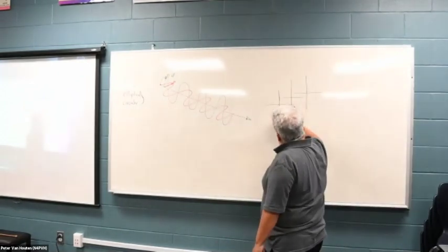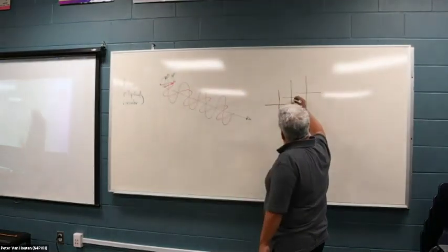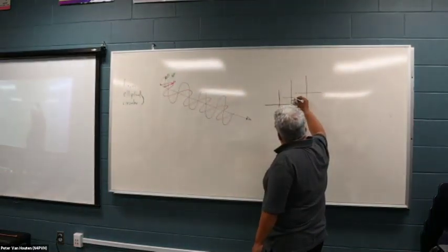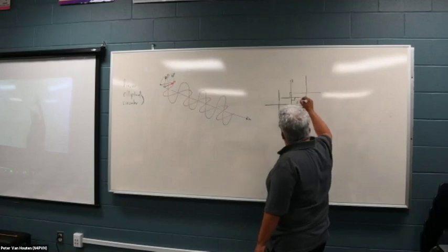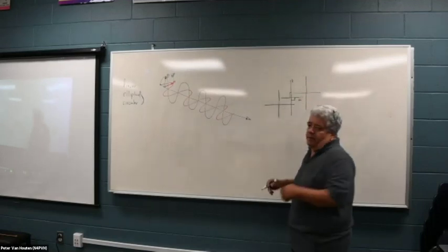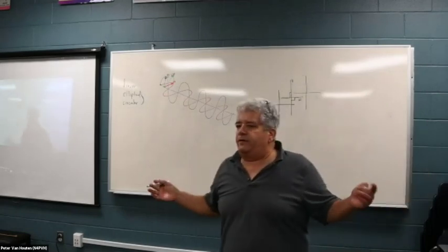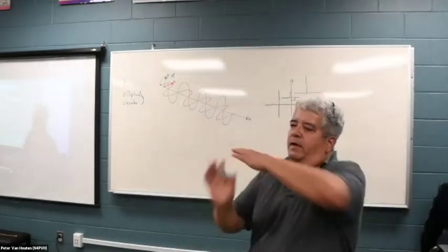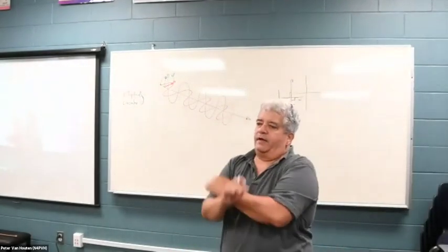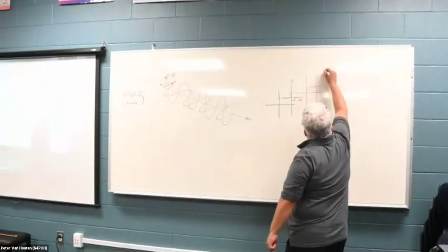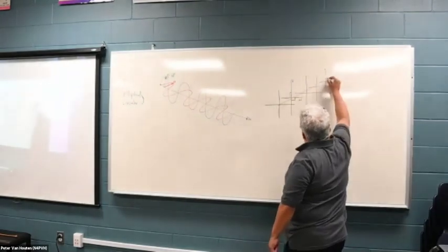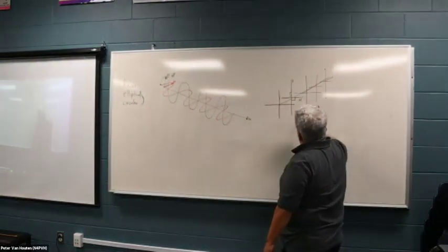So I say that this is my reflector. There are two ways of doing this. And then here is my feed point of one of the horizontal element antennas. And then I can have a feed point for the vertical one. So this is vertical and this is horizontal. Remember, I'm just calling them vertical, horizontal. They are just 90 degrees apart, and it doesn't matter in which orientation they are, as long as they are 90 degrees. Okay? So I have my elements here and the common boom to the antennas.